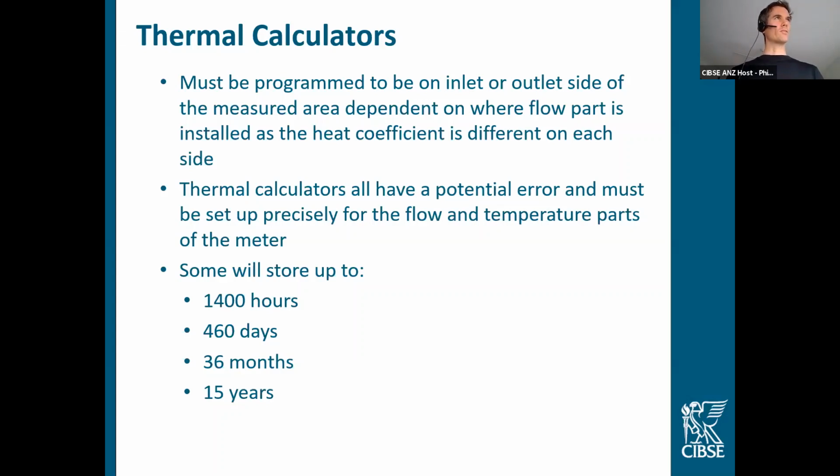If it's purely influenced by temperature, then yes. Why is there an impact on location? I suppose it's to the first dot point on this current slide. Yeah, because the thermal capacity of water varies with temperature. So that K factor is to do with, I believe, the mass of water going past at that point. And that changes with temperature. So it's important that we measure the temperature at the point with the volume, so we apply the right K factor.